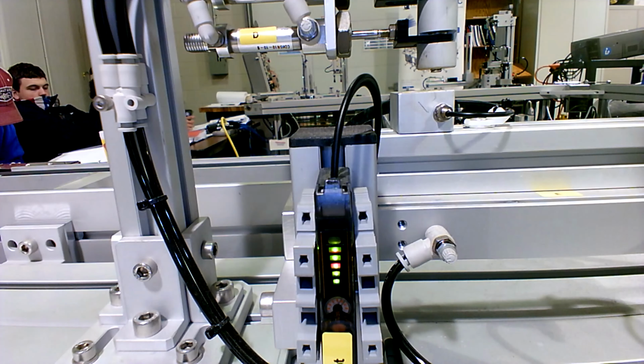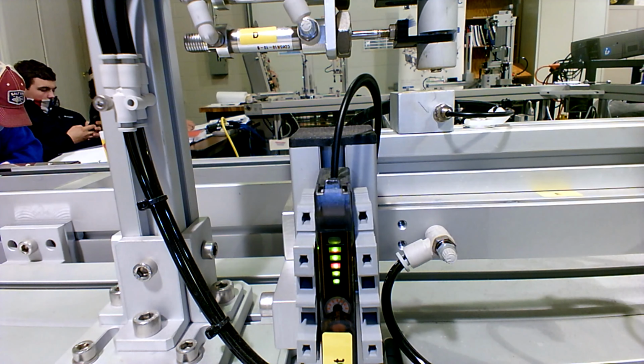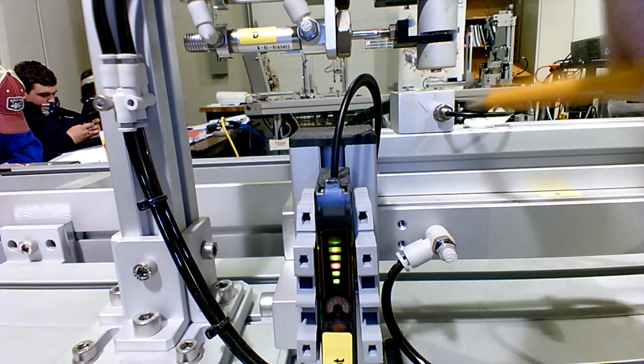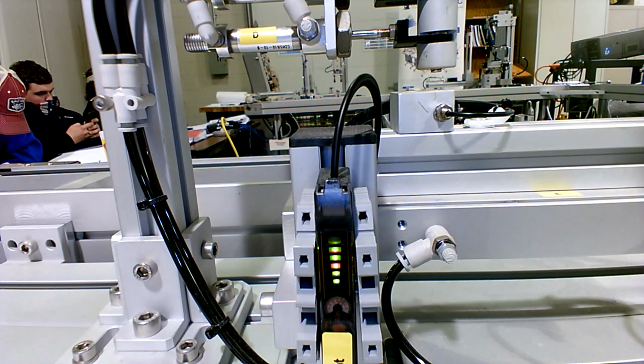You have two fiber optic lines, one that shines it out, the other one picks it up, just like a garage door. On the garage door, on the bottom of the door, you have a transmitter that shoots a light beam across. The other one picks it up, and if the light makes it to the other one, it lets you bring the door down. Okay. This works the same way, but it's got two fiber optic lines that are actually screwed into a block.